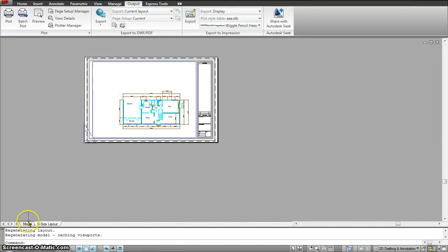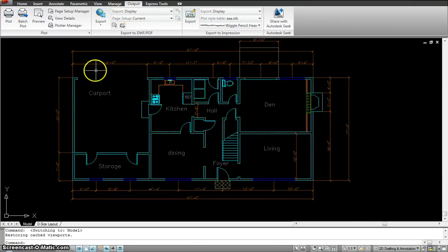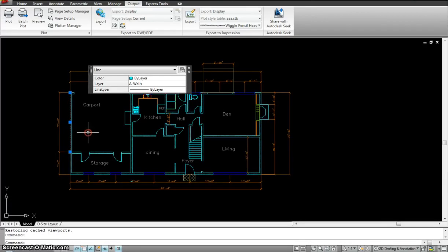Okay, so now when I am working on my drawing, I always go to the model space, and this is where I draw. So if I am making something that is 20 feet, then I draw a line like this. Line is 20 feet. Okay, the scale is 1:1. Now if I were to print 1:1 scale, the exact scale that I'm drawing over here, I would have had to have a plotter that is at least 30 feet wide, right? But again, that is impossible. I cannot buy a plotter that's 30 feet wide.